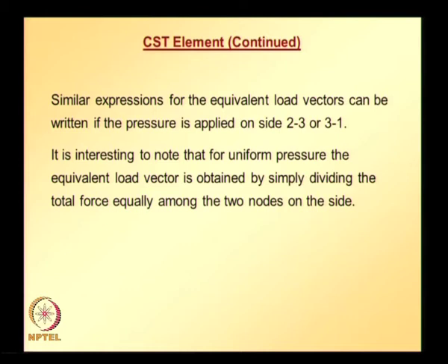So, the total load can be divided into two parts and assigned to each of the nodes, instead of carrying out all this integration, because the traction is uniform and not a function of x and y. So, this is how the equivalent nodal load vector can be evaluated if tractions are specified.